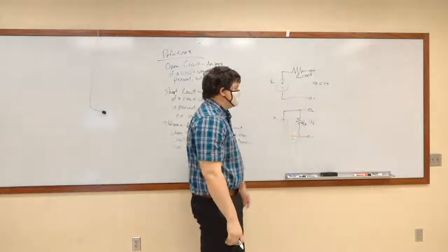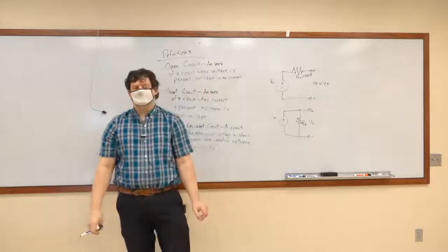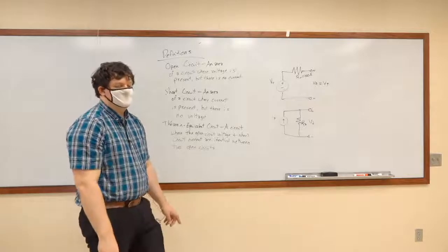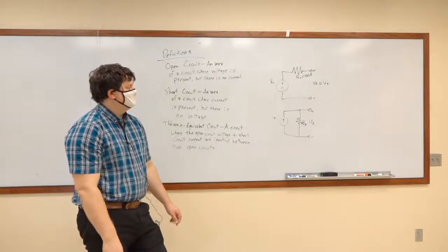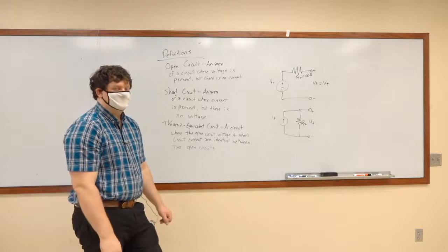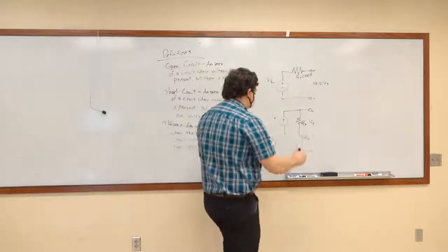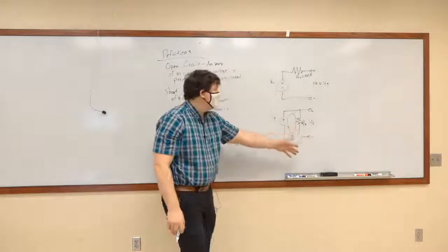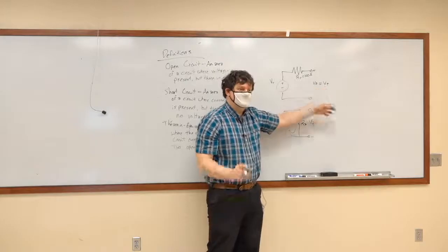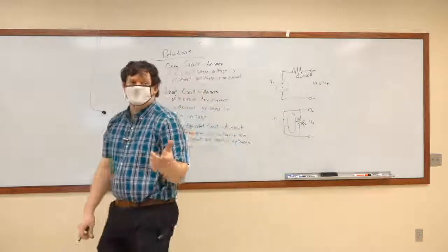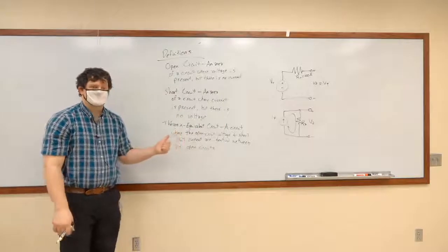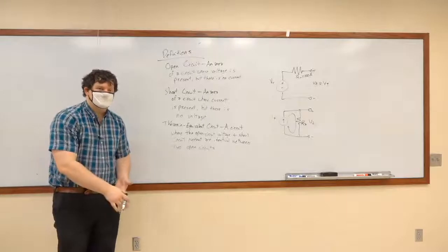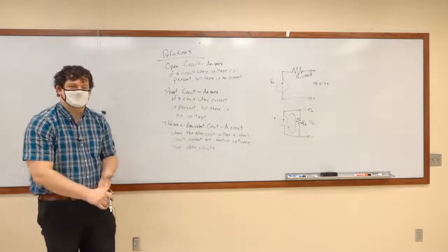How do we figure out the voltage between the two terminals here with nothing connected? Well, we do have one closed loop. And we're loading it in parallel, whereas over here we're loading it in series. Now that's a big deal because if you remember from last time when we introduced current-driven sources, in a current-driven source where you load things in parallel, it decreases the amount of power that's coming out of the source.